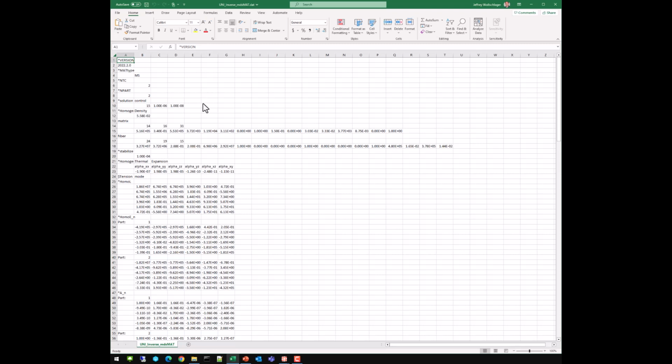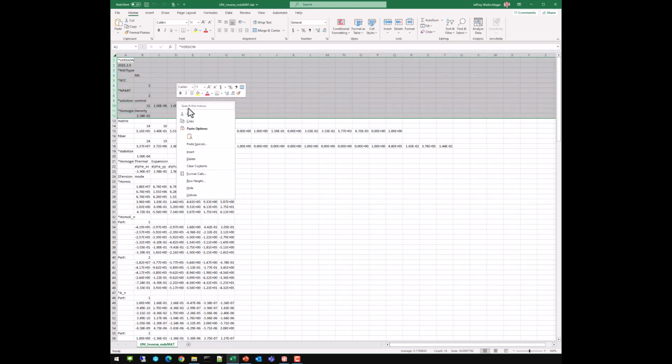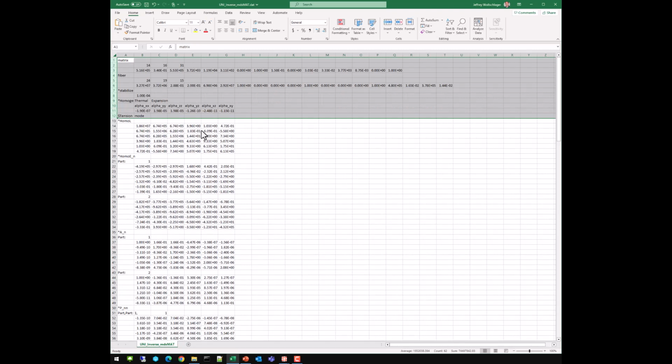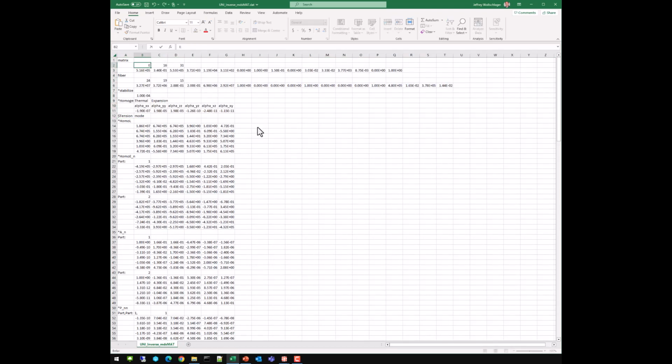And like I said, while you shouldn't have to perform these calculations, I do think it really is instructive and educational. So let's go ahead and get rid of all the data up to the matrix, just because we don't need it. We'll get rid of data we don't need. And the first numbers of the matrix are the Young's modulus, the Poisson's ratio, and the Young's modulus in compression. All the other numbers we don't need. They're associated with the failure law.